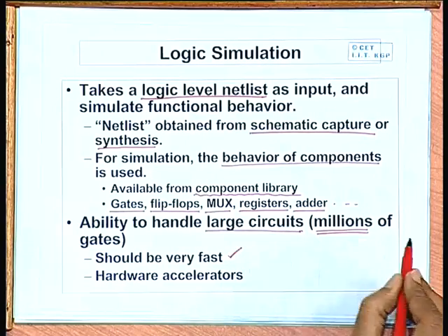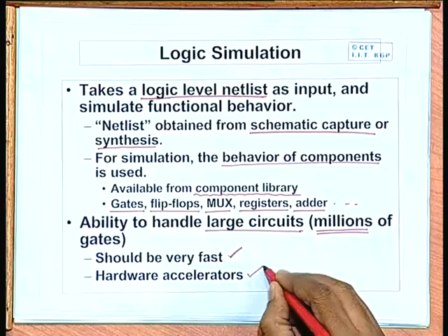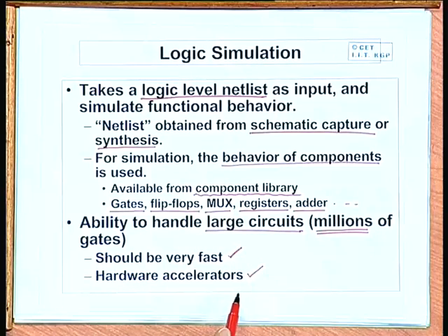To handle such big circuits fast, special hardware called hardware accelerators is typically used, whose sole objective is to speed up the process of simulation. It acts as a helper or a coprocessor to the software simulator. Using that hardware accelerator, you can speed up the rate at which you can process and simulate the gates.